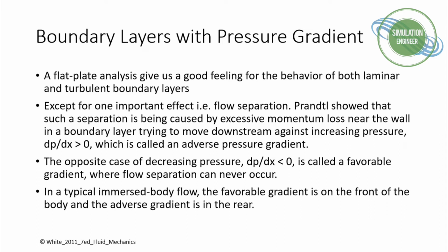If we start with boundary layers with pressure gradients, everyone, even if you are doing your bachelor studies or masters, doing fluid mechanics, has come across flat plate analysis and equations for laminar and turbulent boundary layer flows. Normally, whenever you are doing a flat plate flow analysis, this gives you a good feeling for how the laminar and the turbulent boundary layers behave. But there is one aspect which is missing in this flat plate analysis, and that is the important effect, which is flow separation. This happens in a lot of practical applications, either internal flow or external flow.